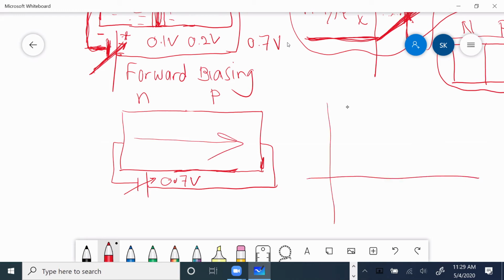So now I want to plot I against V. Initially, as the voltage was 0, there was no current flow. When the voltage was small, 0.1 or 0.2 or 0.4, say 0.4, no current. At 0.6, 0.7, then current. That is 0.7 of a volt.